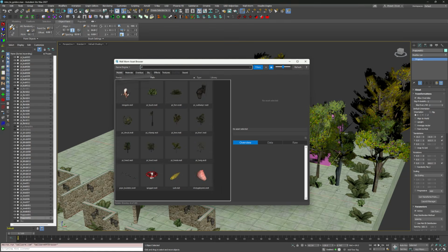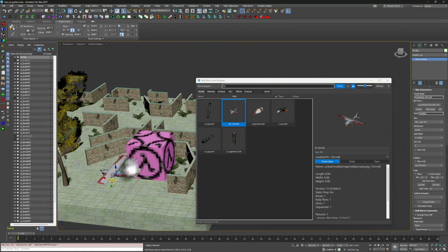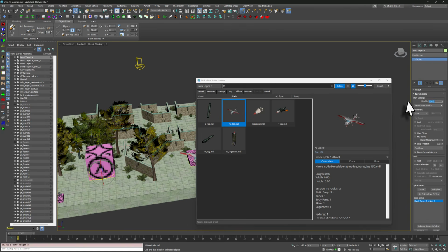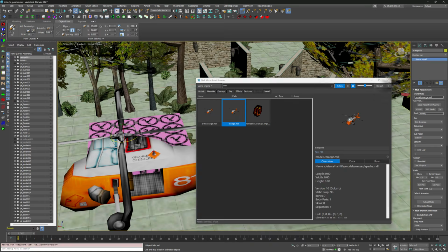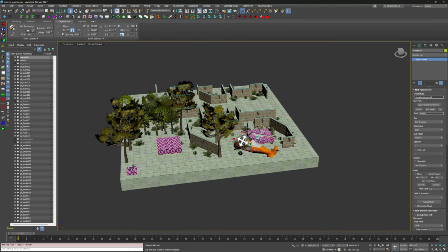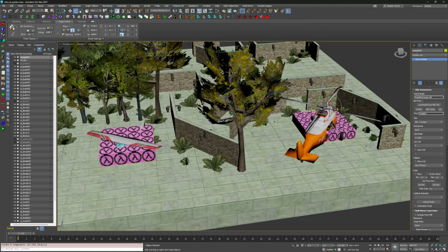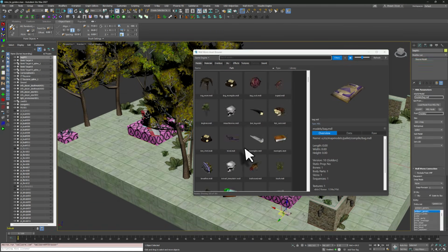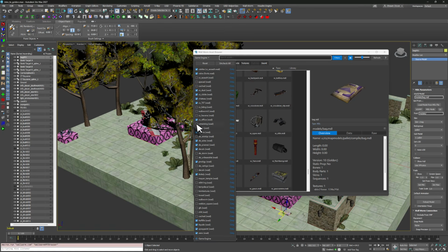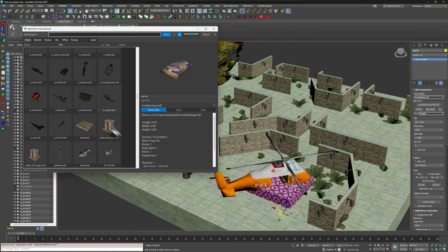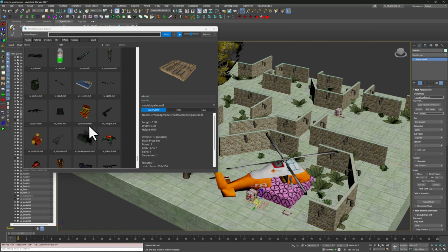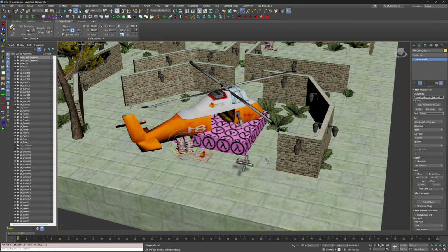Now to add some character, use the Asset Browser to do some set dressing, using the native tools in Max for placement and orientation. Remember to not use the Scale tool for manipulating the props for Goldsrc, as it's not supported in Goldsrc Model. A couple useful shortcuts for this workflow are W and E, W for Translate, and E for Rotation. You can pop back and forth between these to quickly place and rotate your assets.